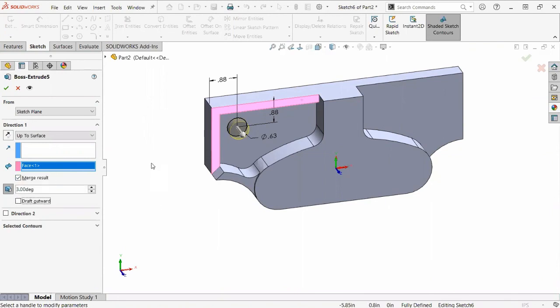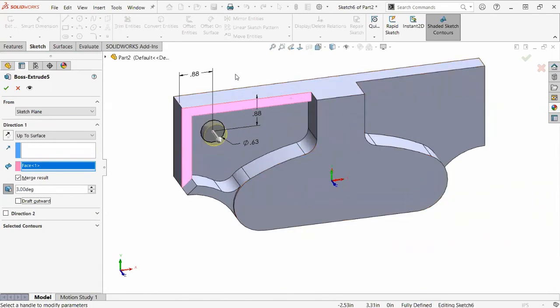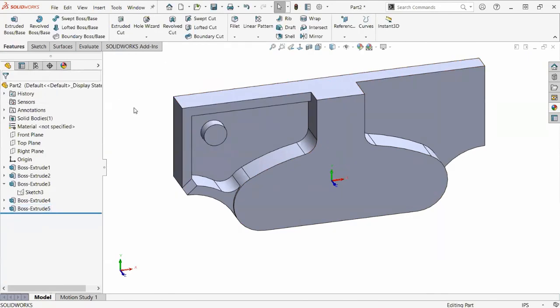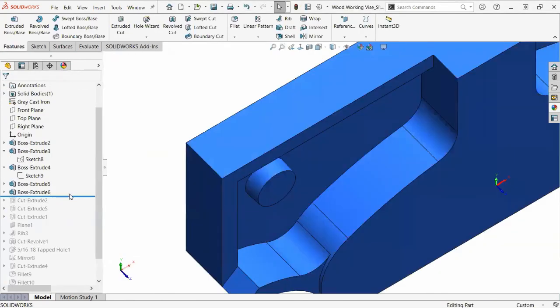That's because parts that are molded sometimes need draft to be removed from the mold. So a little bit of draft there helps this type of occluded feature to release from a mold pretty well. But in this case, it's not really necessary because sand molds are used for cast metal parts, and the sand just breaks out pretty easily. But things to think about when you create parts for molding. That's done. Let's keep on moving.